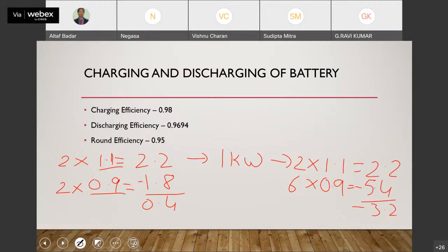The same scenario, on the left hand side and the right hand side. But on the right hand side, the tariff is changing throughout the day. I charged my battery during the night when the tariff was 2 rupees, and I discharged it in the evening when the tariff was 6 rupees. So obviously I'm saving money. I believe you understood that battery charging and discharging can only be beneficial when the tariff changes throughout the day. Without variation, the operation of the battery will actually result in a loss, which is shown here.